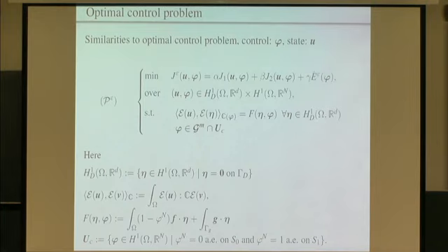And our U C we see here are our sets. Where we prescribe material, we have phi N equals 0, so this will be in a set S0. This was our prescribing material in the domain, and then in our design domain we also might have a region where we want to prescribe void, so therefore we'll have that phi N is equal to 1 in S1. So this is our set U C. Those are the conditions that we want to minimize this problem over.